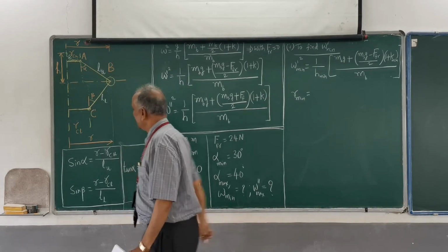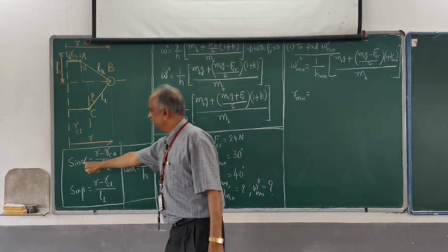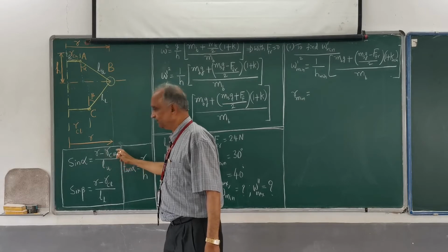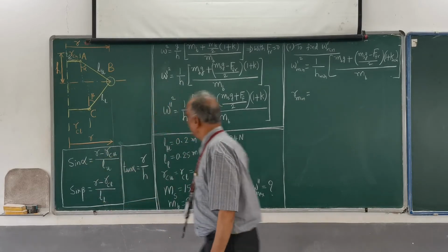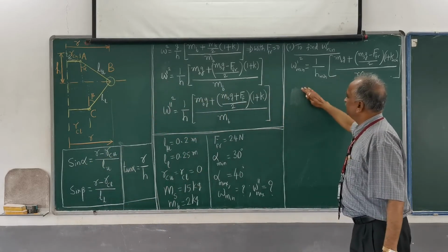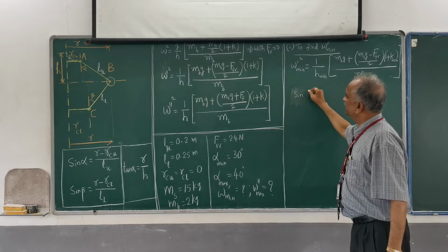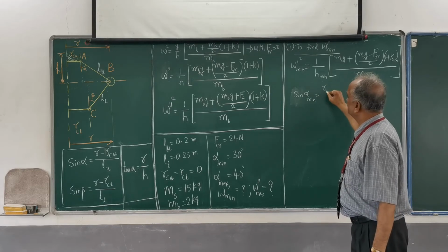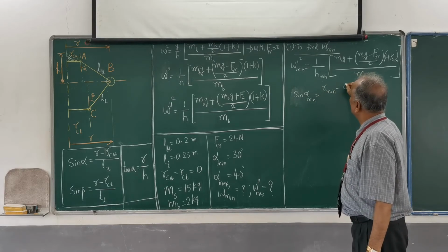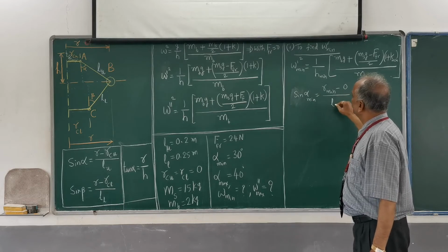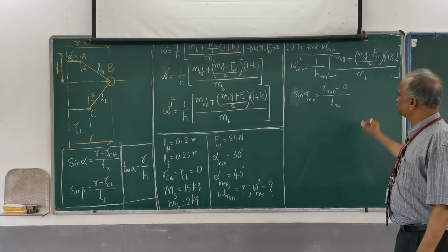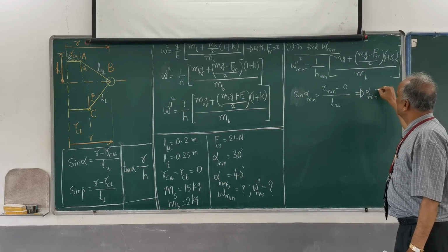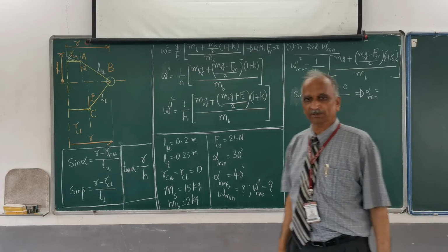So what is r minimum? I can make use of this. I know alpha, so sin alpha is known. Lu is known. RCu is 0. So R minimum can be found from this: sin alpha minimum is equal to R minimum minus RCu, which is 0, divided by Lu.